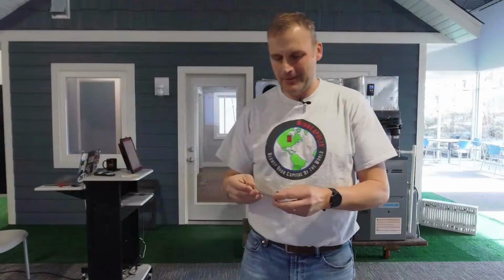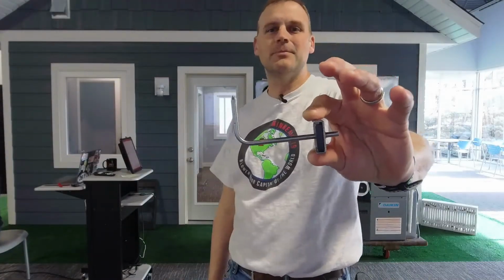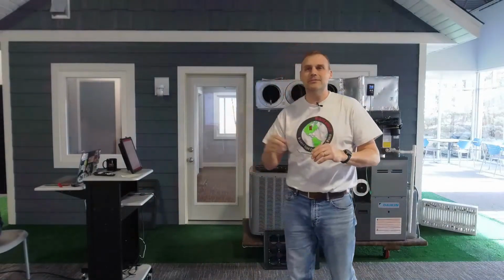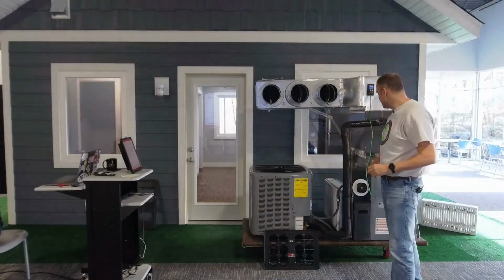All right, so to kind of show you what that looks like, if you haven't seen one before, that is a static pressure probe. They've got some holes right here in it, and there's no hole on the end. So not like a pitot-static tube where you have a hole here and holes here and you're trying to get to velocity. This is just a static pressure probe. We're just measuring static pressure. So this is a lot less expensive than a pitot-static, and we don't need a pitot-static tube for what we're doing. We just need a static pressure probe.